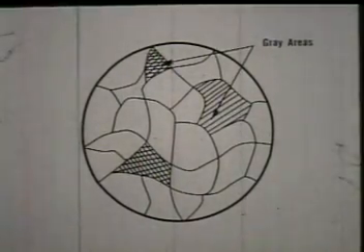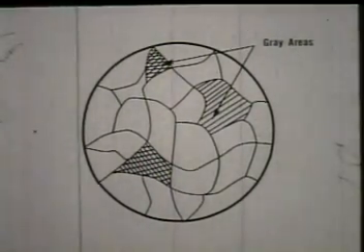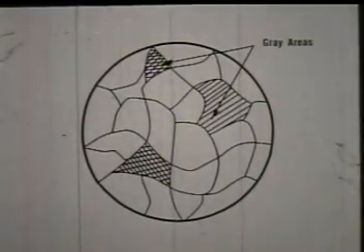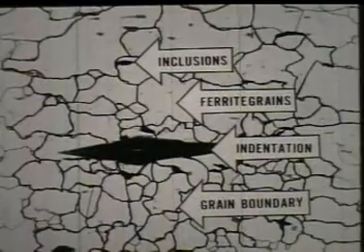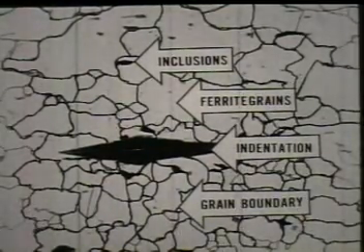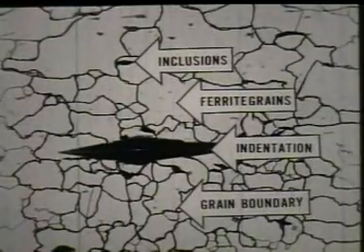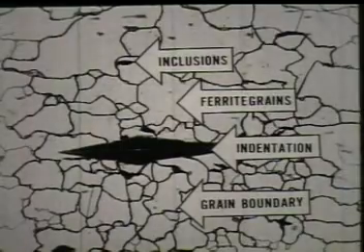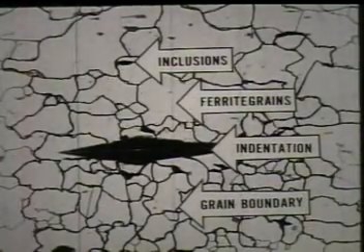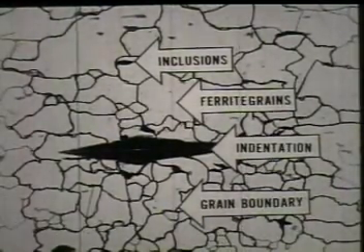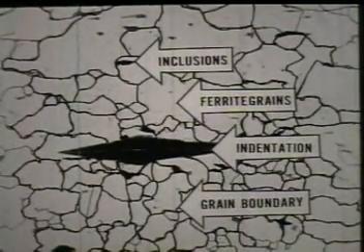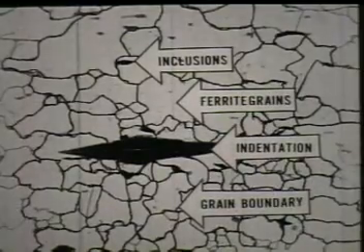If a grain is not a single phase, but rather a mixture of two or more compositions, it will also appear gray. This illustration shows a photomicrograph taken of a very low carbon steel. The grains of the material, known as ferrite, are surrounded by the network of black lines, which are the grain boundaries. The large black diamond-shaped image is a Knoop micro-hardness indentation. The small elongated gray areas are impurity inclusions.